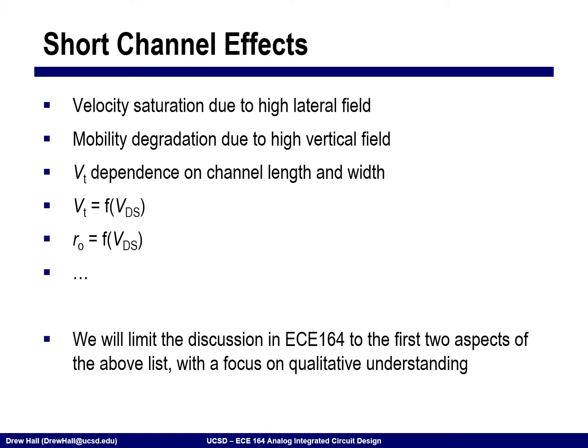This is really due to all of the short channel effects that we talked about back in the device lecture. So we have things like velocity saturation. This is due to that very large lateral electric field. We have mobility degradation due to the vertical electric field. Essentially, we're pulling all of the carriers up to near the surface where it's very rough and we have a lot of defects in the lattice.